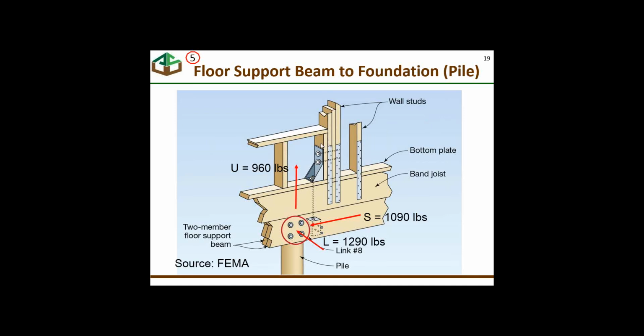The correction there is they definitely resist tension. They are intended and designed to resist tension, and that's why they are connected in this way. When they act in the opposite direction, and this becomes a compression load, the compression is taken into the lumber, into the sill plate, into the floor system, into the beam. So the lumber in these cases is resisting the compression, not the connector.